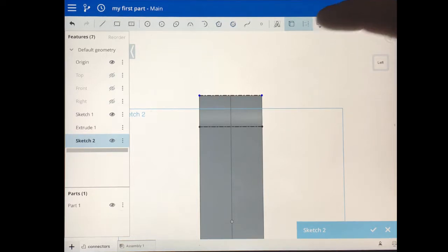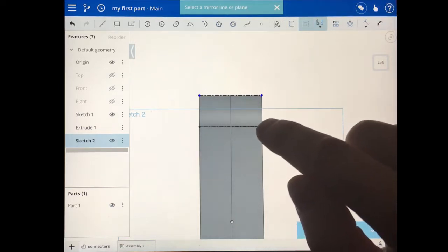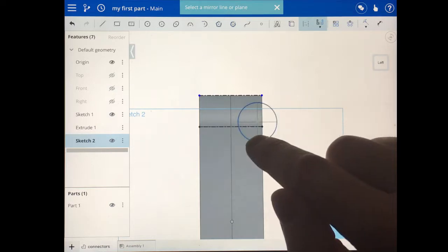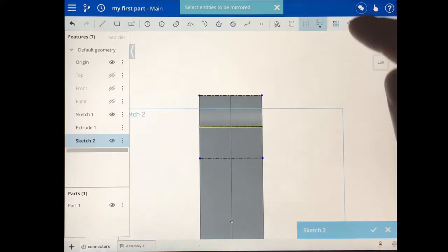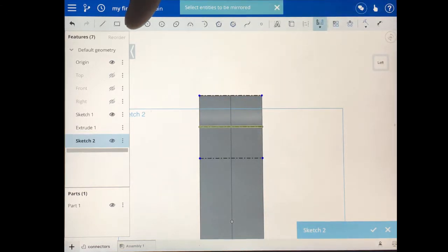I want to create the construction line from these 2 lines, and I will mirror the top line on the middle line to insert the 3rd construction line we need. Next, we actually create the rectangles using the construction lines as reference points. On the top we want to have 3 prongs, so we need 3 rectangles to remove the material.